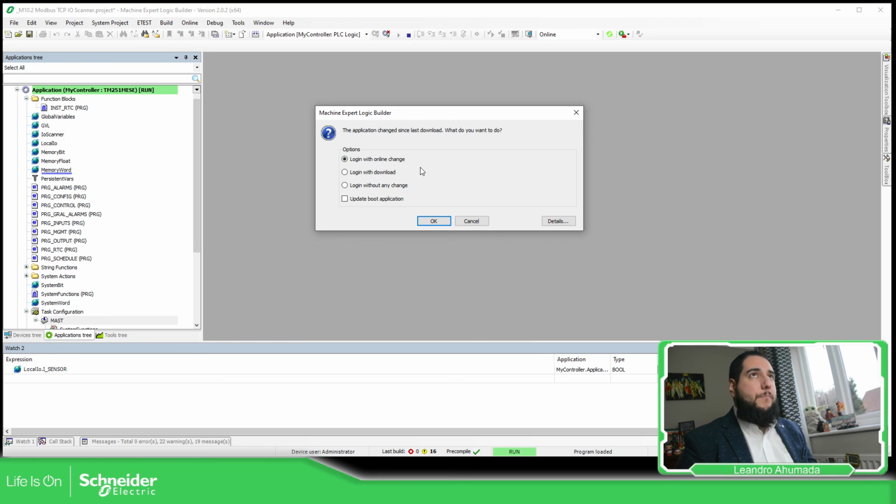This is something that I'm going to check later, but on this kind of PLC, we have a space for the application that is going to run, and another one that stores the binary codes for the application. So when the PLC is power cycled, it takes this stored information, puts it on the RAM, and runs it from there.